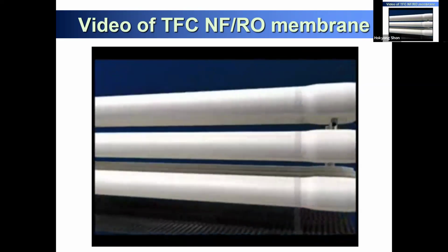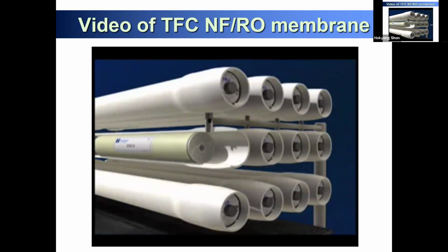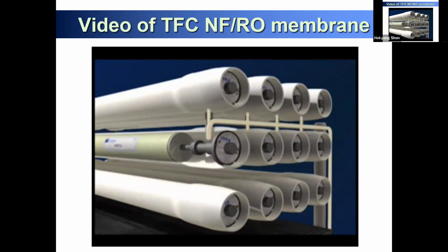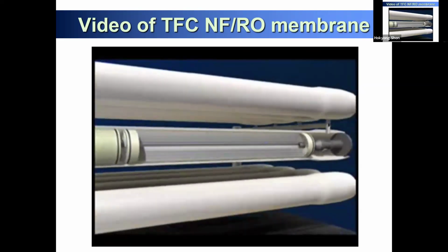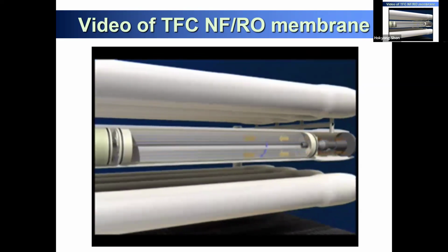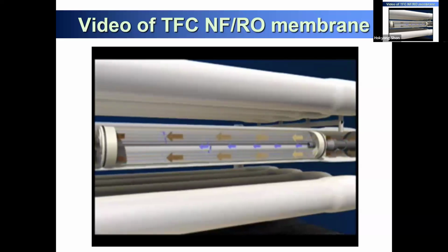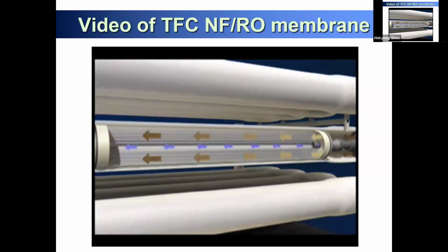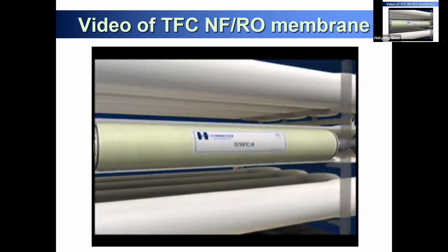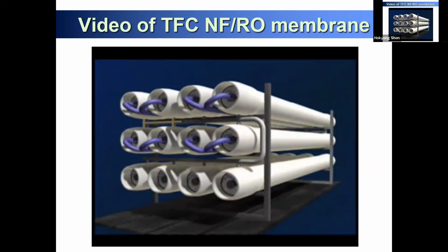Hydronautics spiral wound elements can then be loaded into pressure vessels, interconnected with additional elements to complete any number of design specifications. Once the end adapter is connected to the last element and the pressure vessel is sealed, feed water can be introduced and then treated. The feed water that does not permeate through the membrane becomes enriched in salts as it travels through the feed channel spacer due to permeate water being removed. Typically, 8 to 10% of the water is removed in one 40-inch long membrane element.